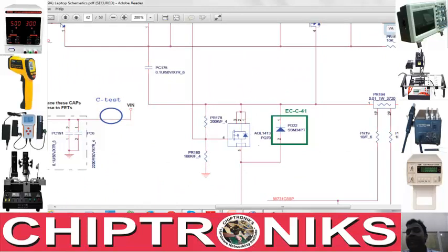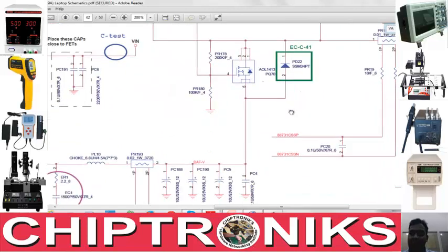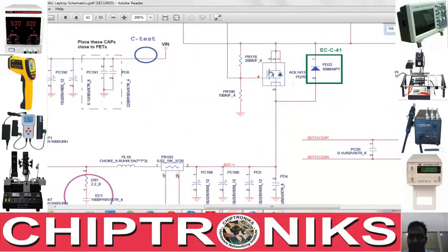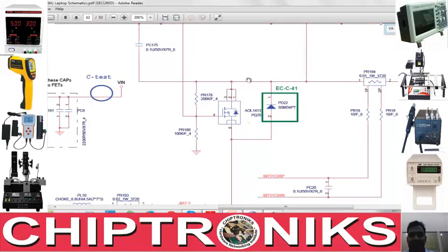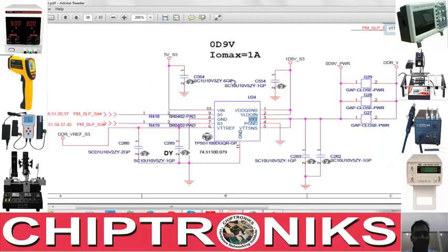So Vin is basically, if the battery is present and the AC adapter is not present, then the battery voltage will come across this Vin, and if the AC adapter is present, then the AC adapter voltage is present across this Vin. And in the i3 board it is called Vin, whereas in the dual core board it's called DC bat out, and we'll check the DC. This is the DV2000 board.